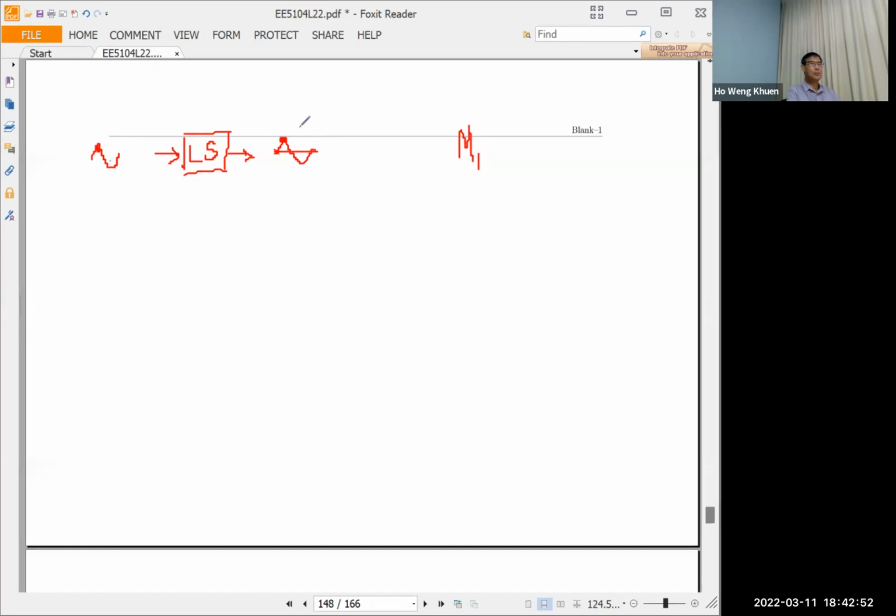Then they ask you to put both on the oscilloscope, and you see there's a phase lag. They ask you to measure the phase lag, which means this one is behind this one by how many degrees. Let's say it's some 5 degrees, so you represent it as phi 1. Maybe it lags by 30 degrees, 45 degrees, whatever.